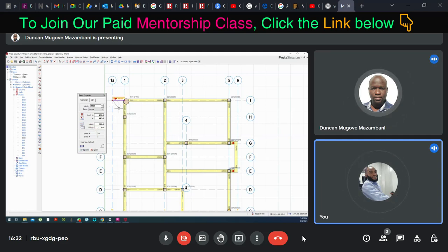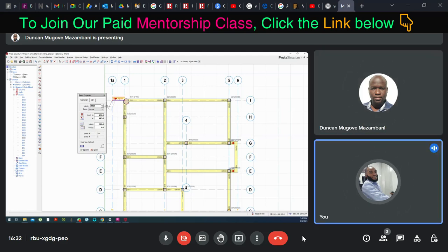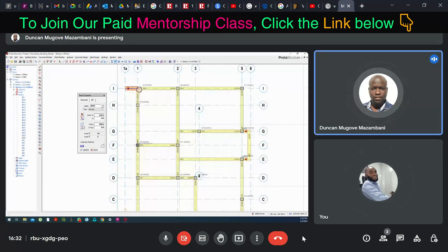Maybe I did not escape. Okay, escape first. Now go back to that beam, right click and say properties. Then choose that place, middle, and update. That's fine. So do the same thing for this grid line F.